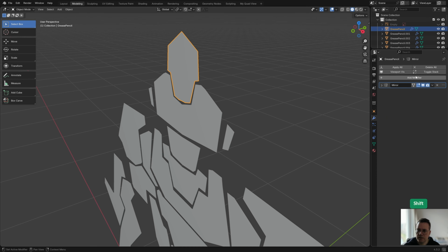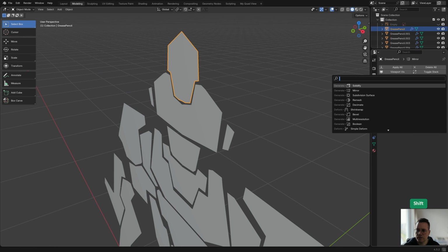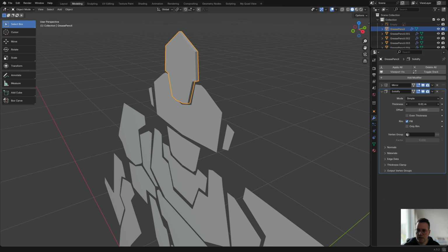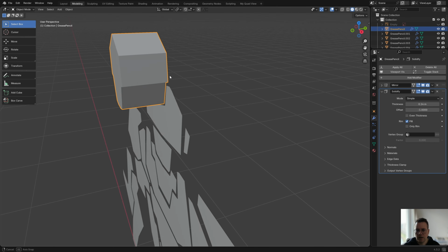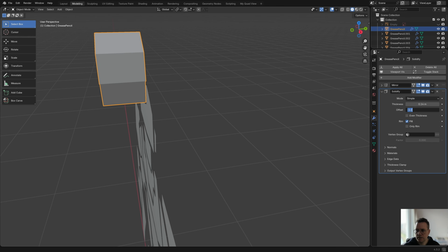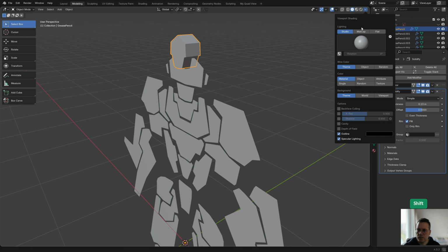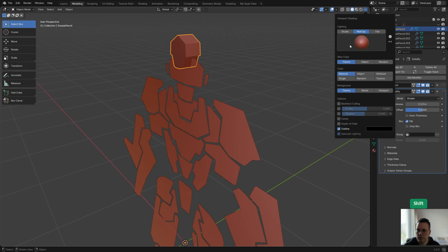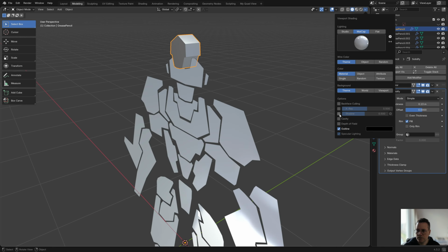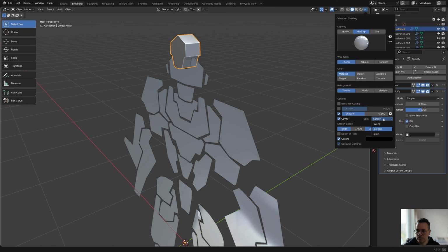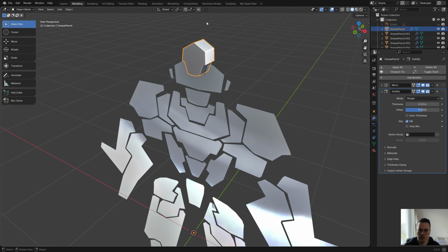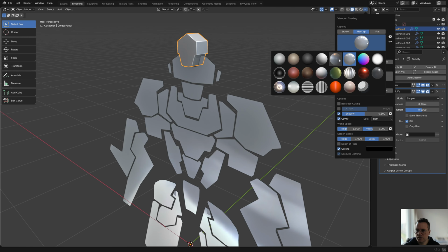And so now we can start adding some thickness to this. So go to search and solidify, and then just increase the thickness. And instead of it going forward like this, we can set the offset to 0. Then it just makes the thickness from out of the center of the object. Let me just quickly turn a matcap on so that it looks more interesting. And I'll also turn on cavity and shadow and set this to both. That just looks better. Maybe let's use a different matcap.